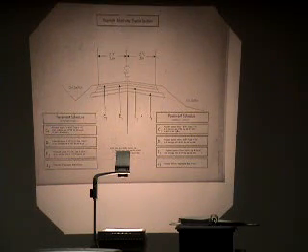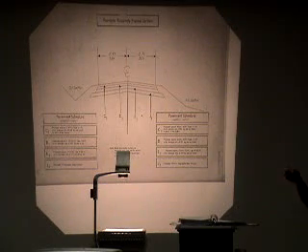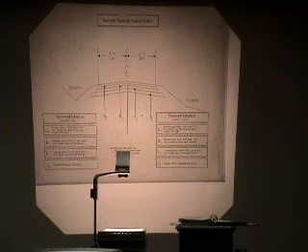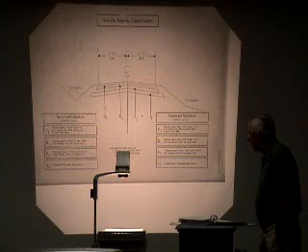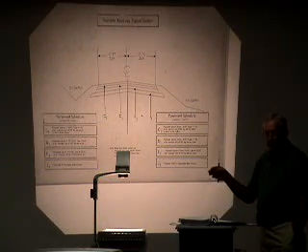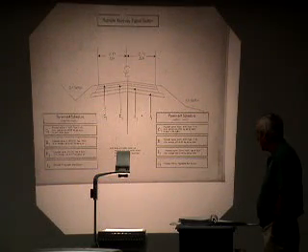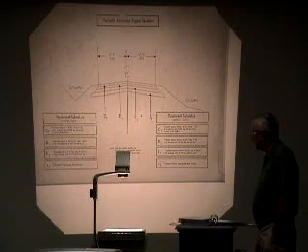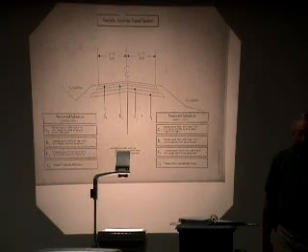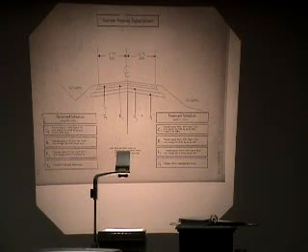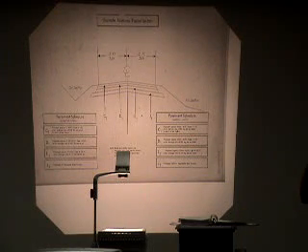It'll always tell you a mix type, an average rate, and an approximate depth. In this case, it's talking about a proposed 3 inches of ACSC, that stands for asphalt concrete surface course, a type S9.5C at an average rate of 168 pounds per square yard in each of 2 layers. Now, why does it say some approximate depth and some average rate?